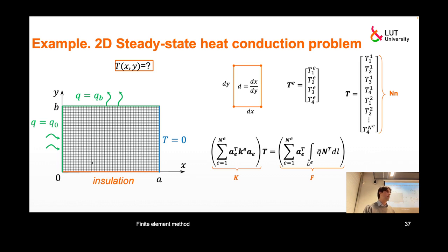Of course, this type of problem you can probably also solve analytically, but you can easily extend this problem to a little bit more complicated one where analytical methods might not work anymore. Okay, so this is my mesh. I will actually use a rougher mesh with a lower number of elements, for example, to show you how the matrices look, but this is how it may look in general. We will be able to vary the dimension of elements in our code, and this is the element I will be using. The same rectangular element.